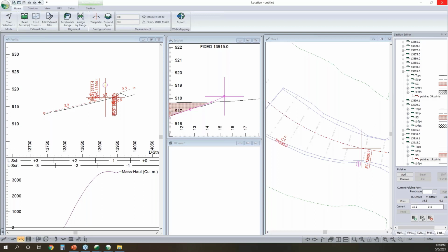Now, the limitation of going with that approach would be if you have an irregular original ground surface, it's going to interpolate the volume based off of an interpolation based on the boundary. So if you dug a hole and the hole was originally a mound of dirt, it's going to project that volume being a planar surface around the extents.